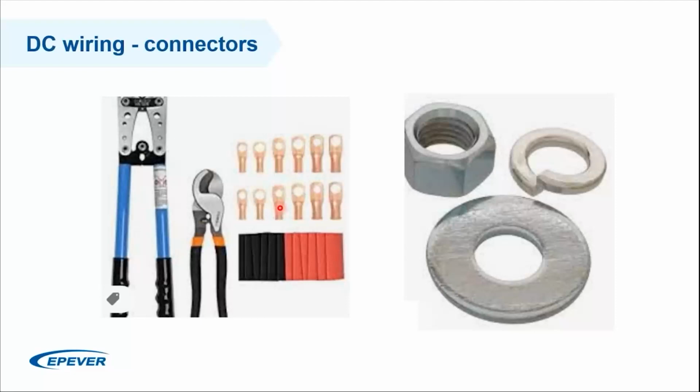So you have a very high resistance there at your joint, and it will get warm. And yeah, we have seen a lot of failures in the field because of this problem. So the tools that we are using for pressing the lock to the cable and the amount of the insulation and making it water and moisture resistant is also very important.